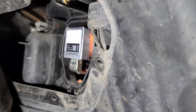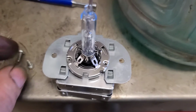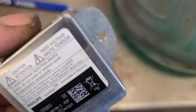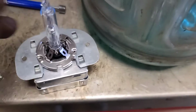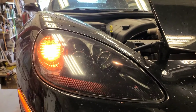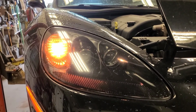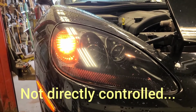Now we're going to try another bulb in there just for the hell of it and see what happens. So to get the bulb out, there's two little T10 screws that you have to remove, and be careful not to drop them inside the headlight assembly. Use a magnet, and then this bracket comes off and goes on the new bulb. The bulbs don't have a filament. It's an electric arc across this xenon tube. Well, that's not good. So we're going to have to check the wiring and see how this thing is designed. There were no codes in the body control module, but I'm not sure if that's body control module controlled or not.